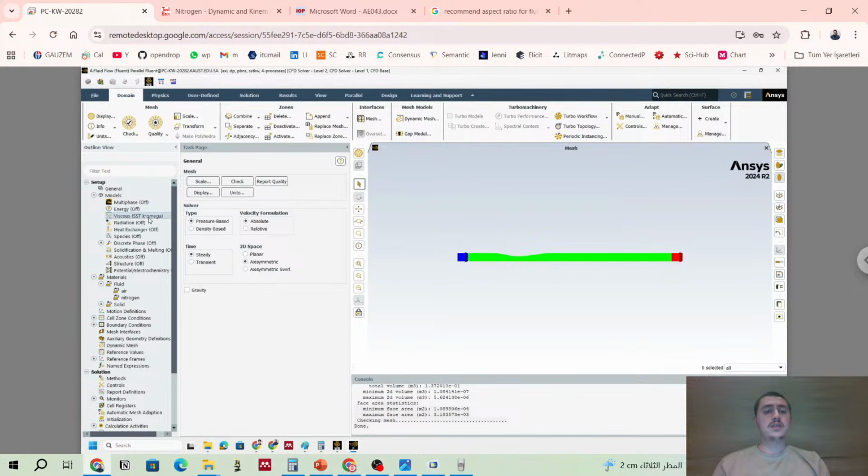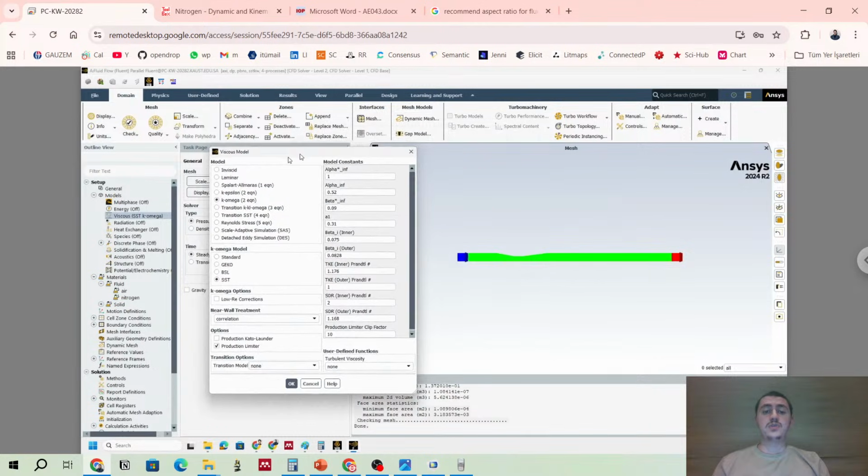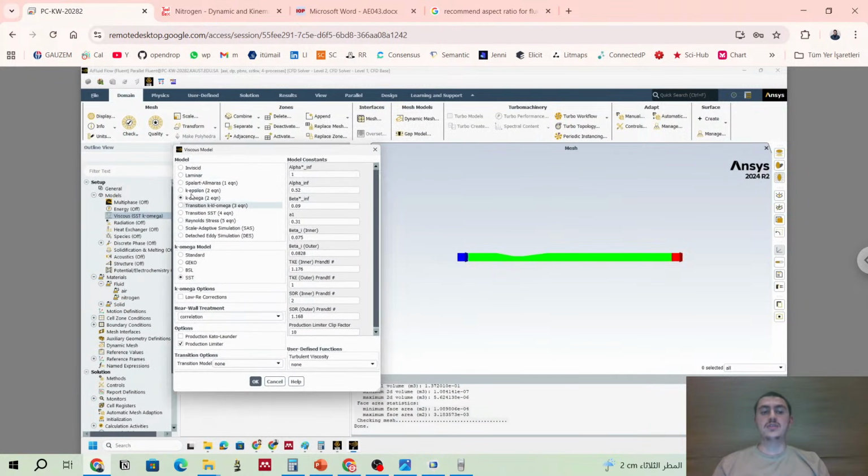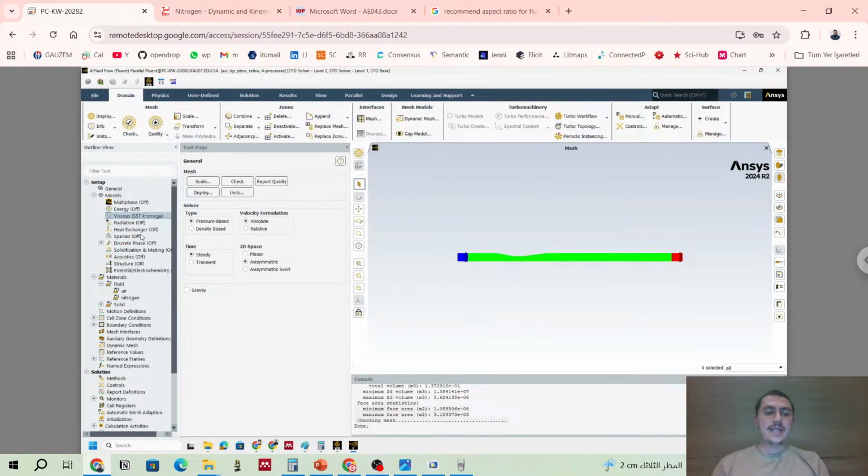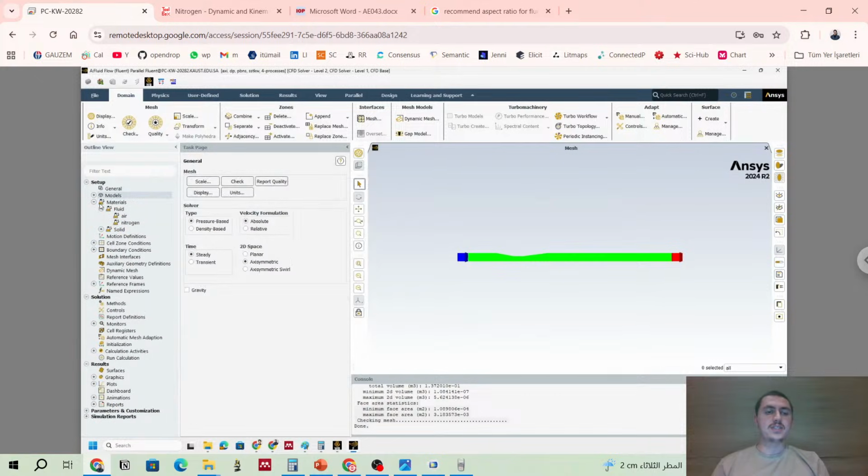So the viscous model is the single phase fluid dynamics part. I should have a viscous model, a turbulence model that solves this problem. So let's say k-omega is nice for this problem now. We don't change anything. Our turbulence model will be k-omega, and we say okay, and we don't add anything. Our model is nice, just close it.